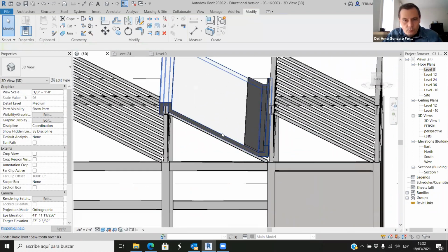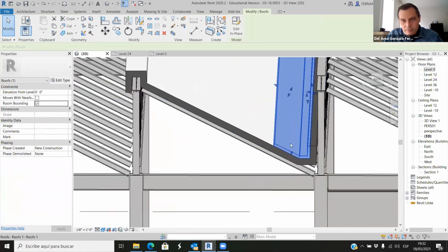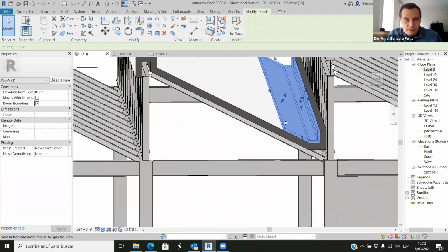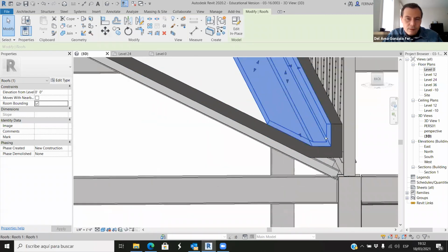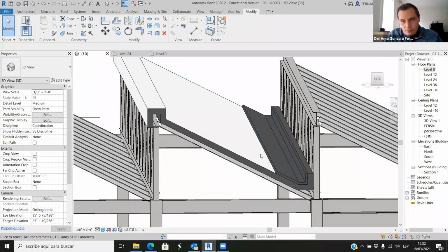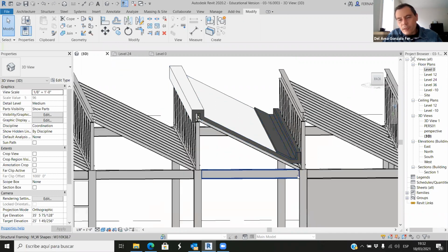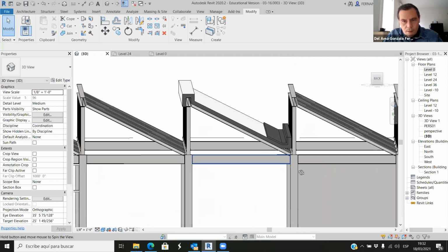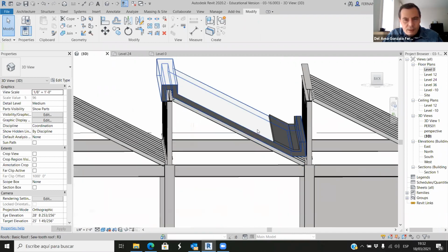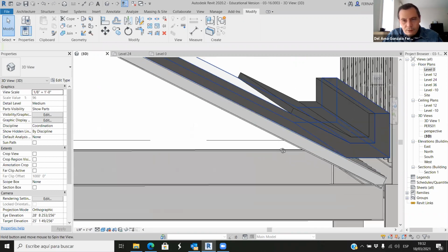Okay, now I have the roof. I have this gutter that is made of material that is more resistant, probably thicker. So this can be made of galvanized steel or lead or some resistant metallic element that can bear all the water that is coming in this direction. Okay, are we done with this? We can make it better because now look at this.